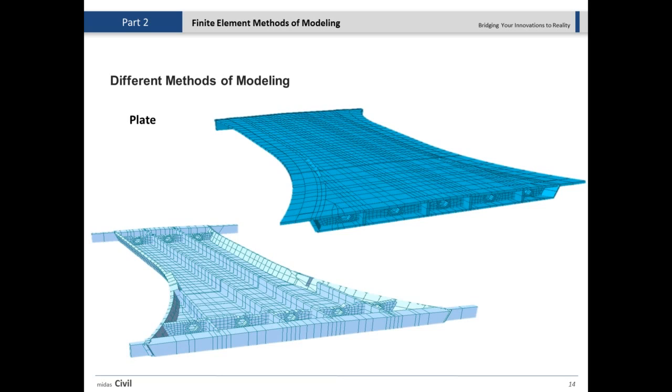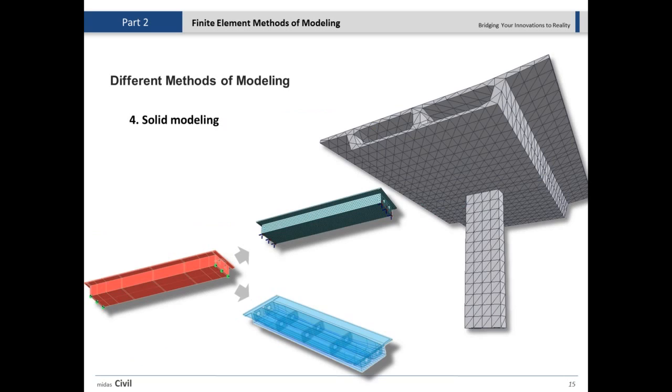When we model this with a plate element, what we have to consider is the importance of correct modeling for post-tensioning. In the beam model, we can simply run the post-tension cables or strands, post-tension them, and get all the effects. In this way, when we have plates, we have to use some other skills to directly post-tension the structure in the correct location. Okay.